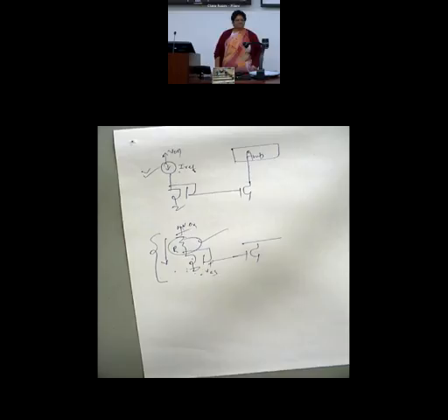VDD fluctuates, IREF fluctuates. And I bias is a mirror of I reference, so if I reference is shifting, I bias will shift. If I bias shifts, my Q point will shift, and on my Q point depend all my small signal parameters: GM, RO, GMB. They depend on the bias current.